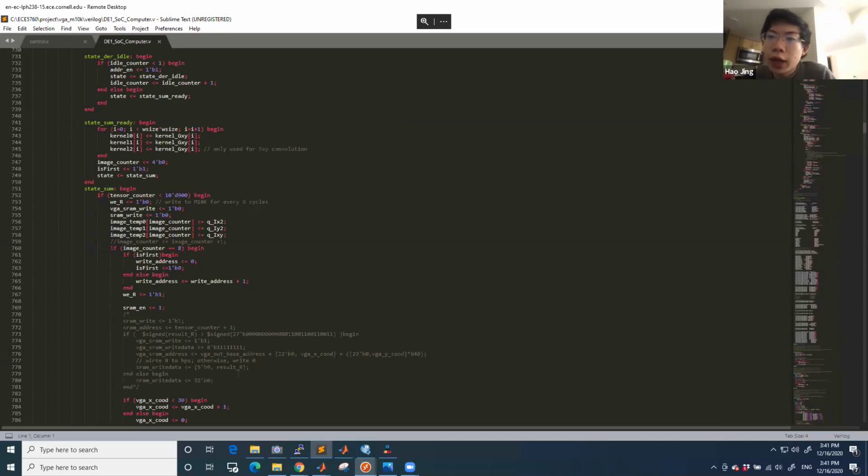That's why we chose to normalize all the grayscale pictures. After several experiments, we think 6.21 is a good format for us, so we finally use the 6.21 fixed-point representation for our calculation. So that's the whole flow on the FPGA side.